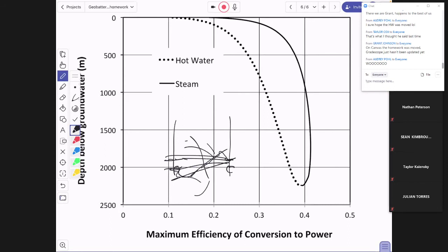I just bring up the pressure in that steam zone. If I'm bringing up the pressure, I have to bring up the temperature because they're connected. To bring up the temperature, I have to get energy from somewhere, and it gets it from condensing steam. So essentially what I've got are these condensation waves that are propagating through this material.